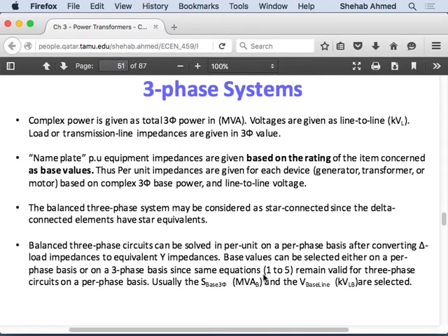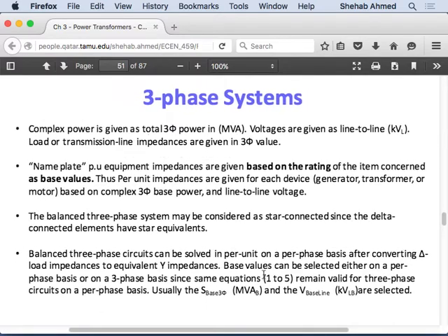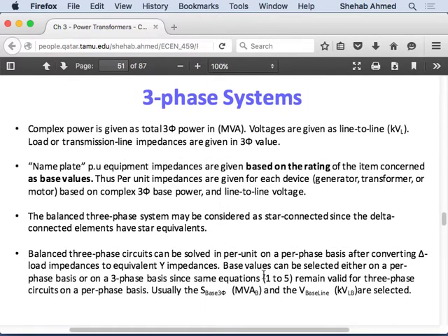This example was in single phase, and most of ours, you were given voltages as 240 and 480. You were not given a three-phase system where we will start confusing you with the root 3s and the phase shifts. We will add delta transformers later, and there will be some phase shifts as well. If you're given line voltages, you're constructing the single-phase equivalent circuits. Remember, in a three-phase system, the same thing applies. Per unit applies the same way in three-phase.